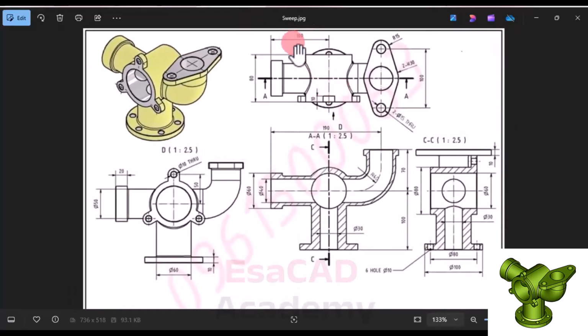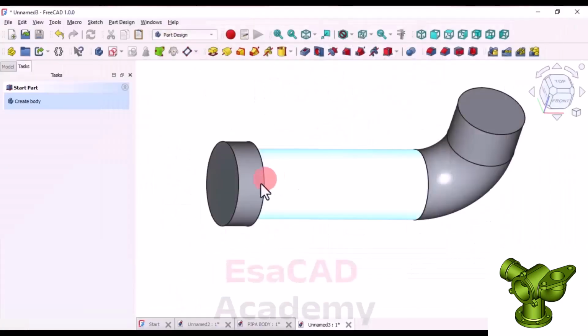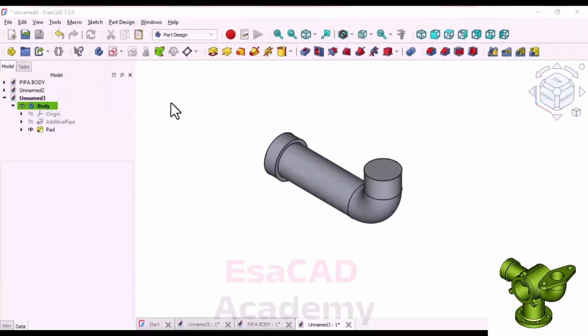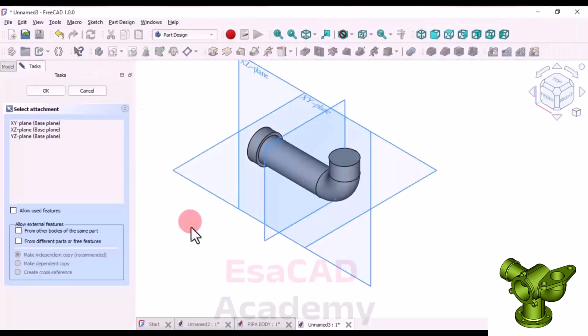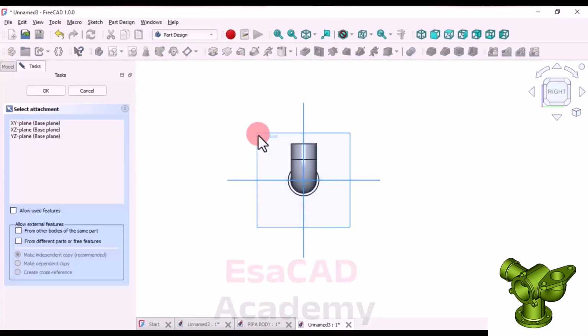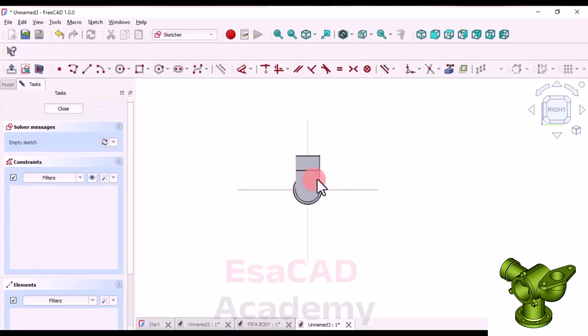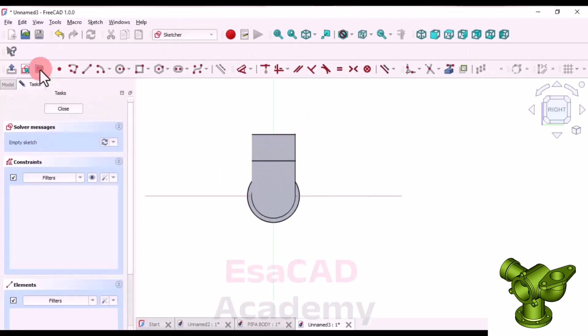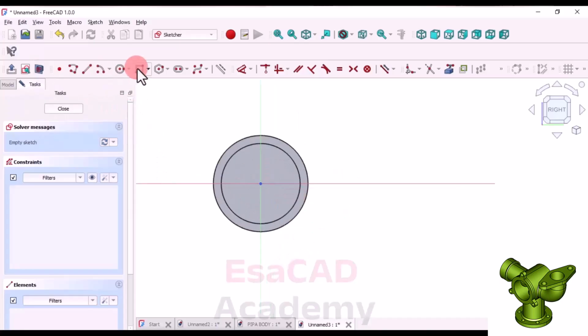Now set this value to 100 and the other one to 80. The diameter is 80 millimeters. Okay. For the distance on screen, 100, let's select it. When we set the right plane to right plane here, and also configure the Z plane to Z plane, we then proceed to view it halfway, so that we can clearly see the necessary adjustments. Next, we proceed to create a rectangle.